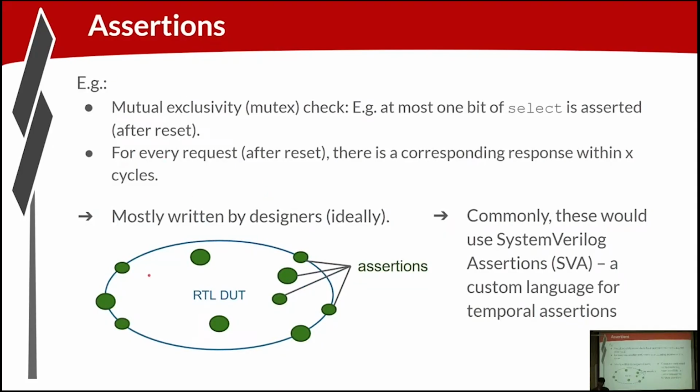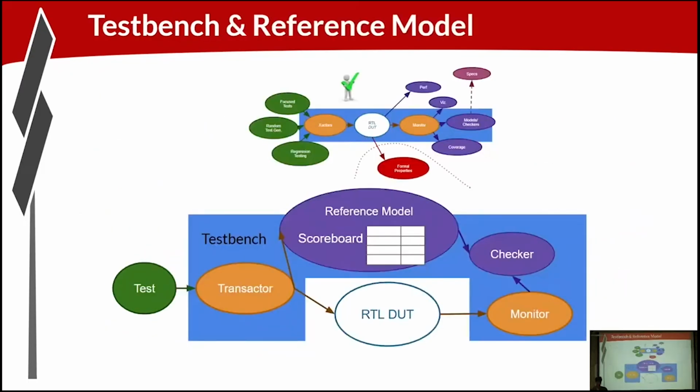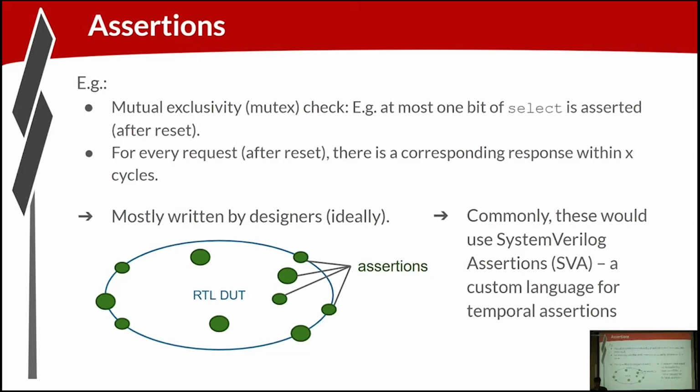Assertions are very low-level checks that might be internal in your design, right? A lot of our verification is focused on treating something, for the most part, as a black box. So you don't care how it's getting done, what's happening internally. You just want to make sure that the behavior that you're seeing from the outside is right. Assertions, they can be internal. You sprinkle them everywhere. Assertions are not your level of completeness for verification. Assertions are identifying bugs as close to the source as possible. They're capturing design intent.